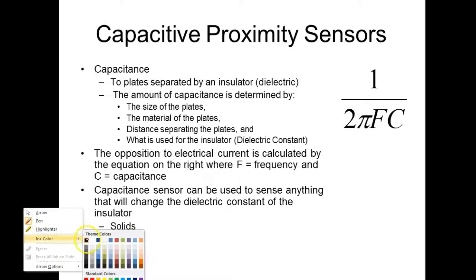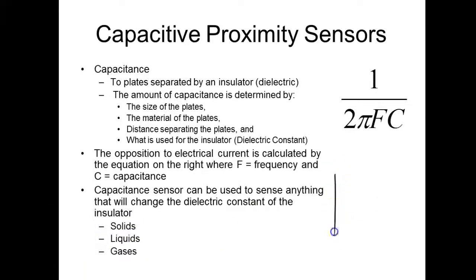So in motor controls, we have what they call solid state sensors. So you look at this, I have this solid state sensor. Normally in motor controls, we'll put it inside a diamond shape. So if you're ever troubleshooting a motor control circuit and you see a symbol inside a diamond shape, it means it's what? Solid state.